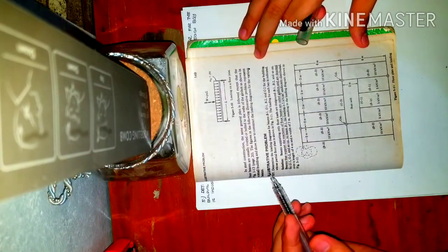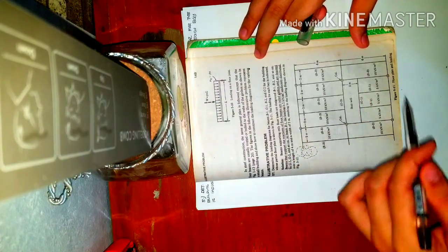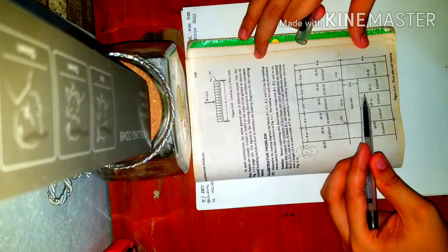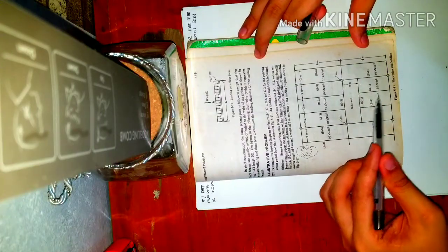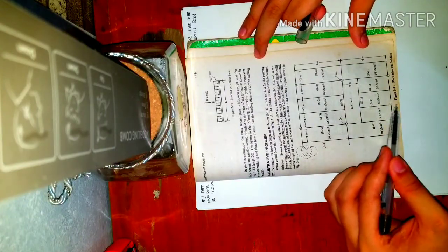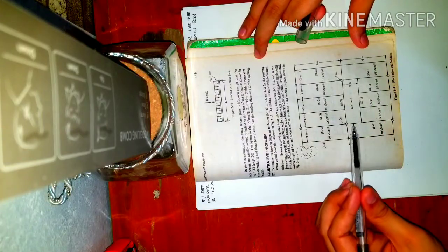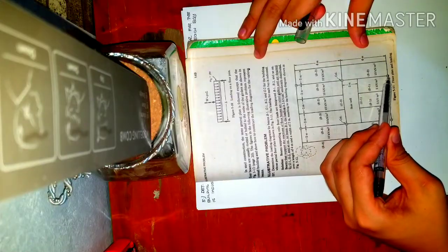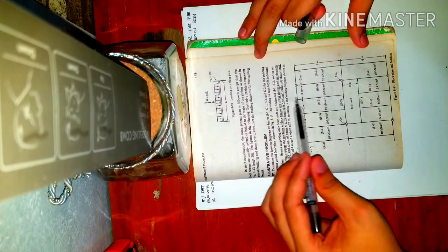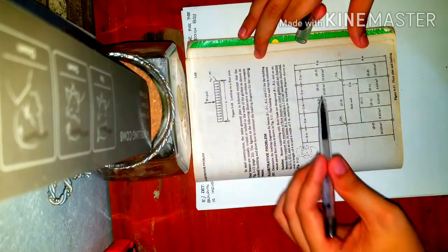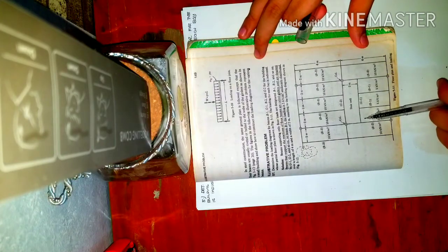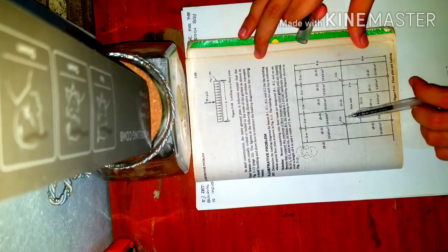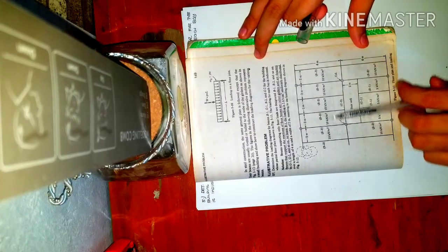So what makes up this floor framing plan? First, you have beam 1, and there are two of them. You only need to compute one, since both will have the same loading. Next, we have beam 2, these two, and then beam 3. Aside from that, we have two types of girder, G1 and G2. Again, the girders are where the beams rest.